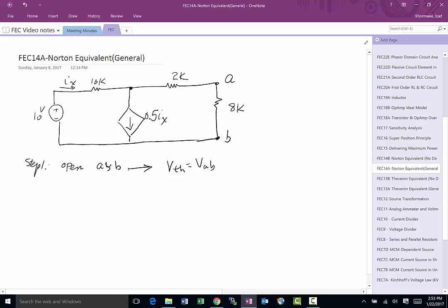So we say, okay, the easiest one for us to do here is KCL, or the node voltage method. We're going to call one of the nodes V reference, and then we'll name this one V1, and we'll name this node V2, and that's all the nodes. Actually, to be exact, this is not an essential node, so we can literally leave it alone, or you can include it. In this case, it's a little bit convenient to include it, but there's only one essential node.